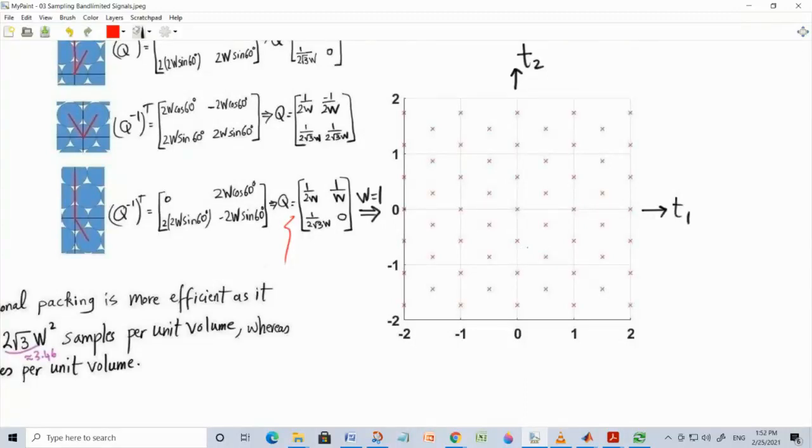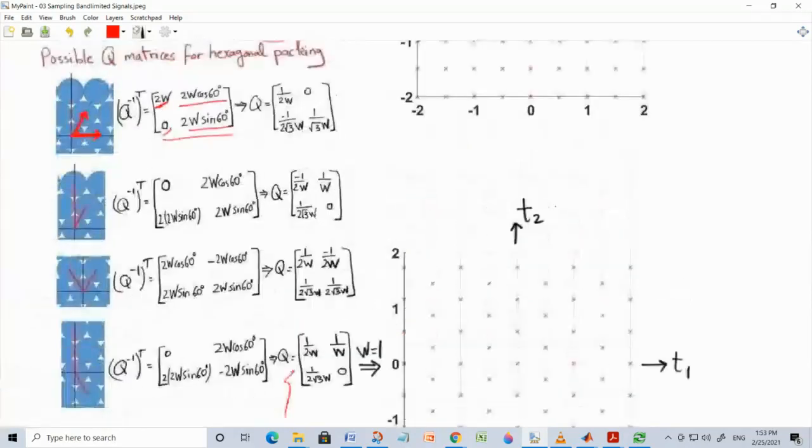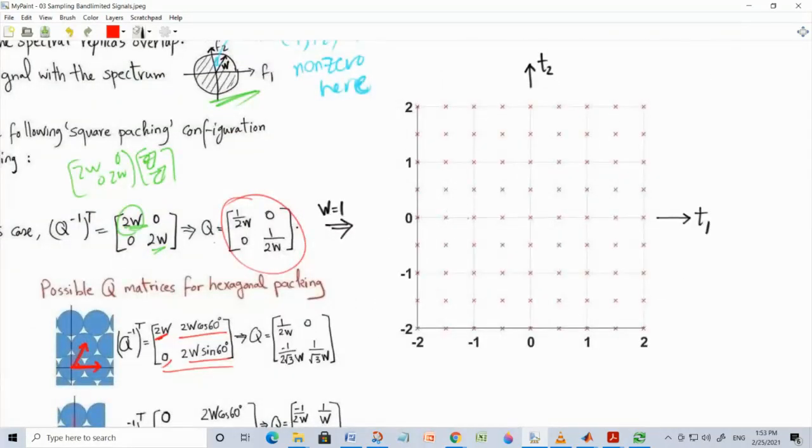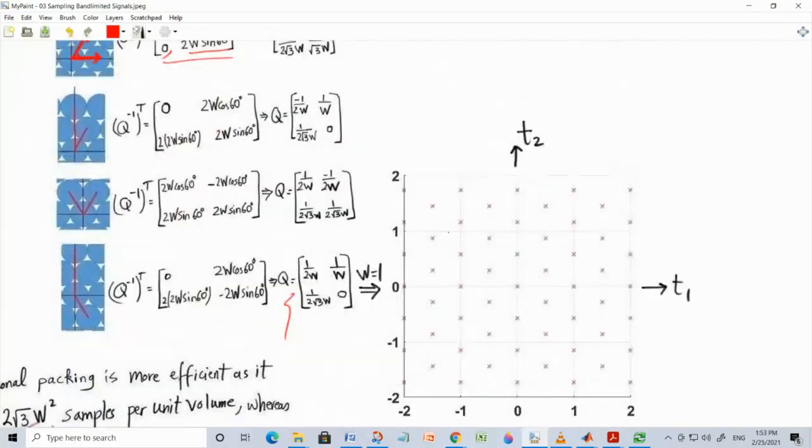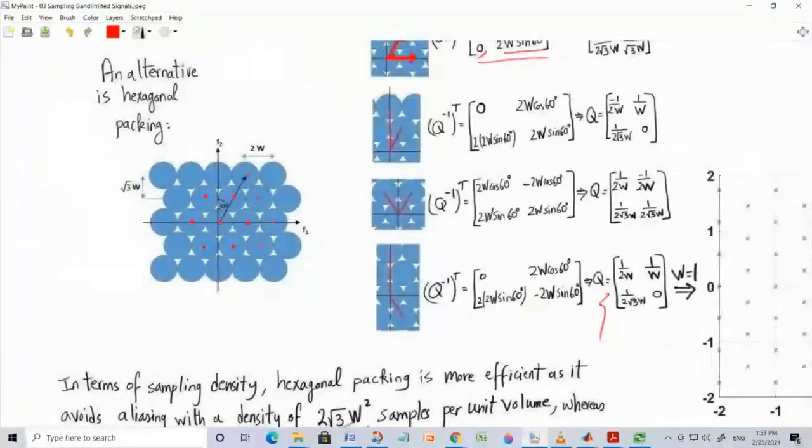As you can see, you also see the hexagons here. This is the pattern in which you sample your two-dimensional signal. And if you sample using this pattern, I can compare it with this one. This one is the straightforward one, which comes to your mind. Basically, you do sampling with a certain interval along each axis. Here things are a bit more complicated: you take this sample, along this line there is a certain spacing, but then you do a shift like this. So this sampling again will result in this spectrum.